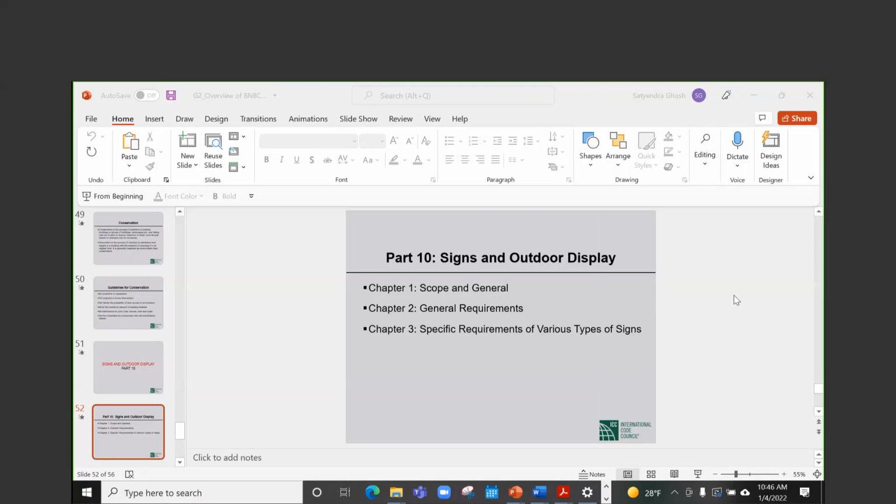Nowadays, 60 grade rebars are not available. Most of the rebars found are 72 grade, but special moment frame structures, especially in seismic zones 3 and 4, are restricted to 60 grade. So what should I do in such a situation?